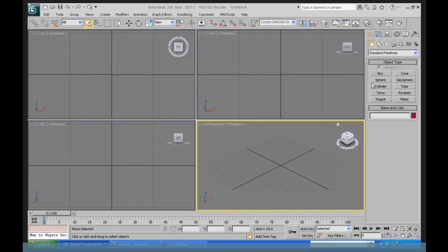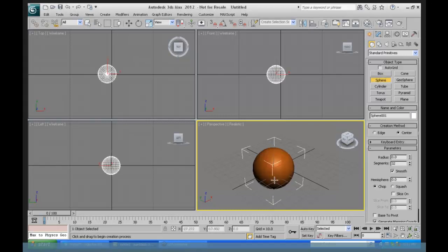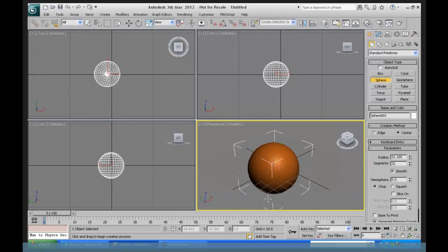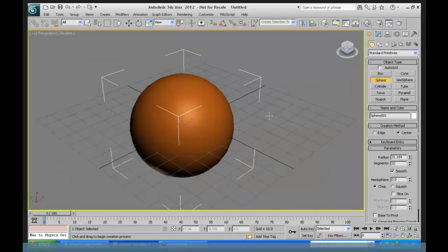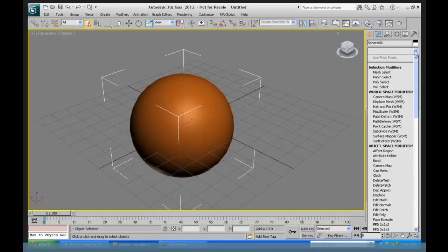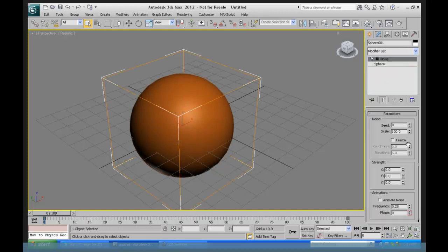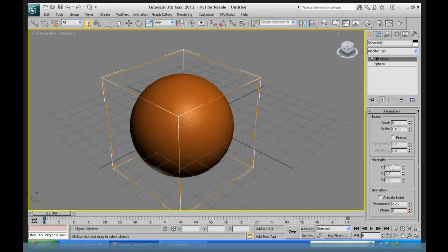using modifiers. Real quick, since you asked for that, I'm going to give you a demonstration of one simple tool that could be used for creating this. The same technique could be used to create a rock wall. So here I have a sphere, and then I just put a noise modifier on that sphere. With a noise modifier, if I change the scale of it so it gets down, oh, hold on, I've got to have some strength in it. Let's say 22, 33, 44, like that.